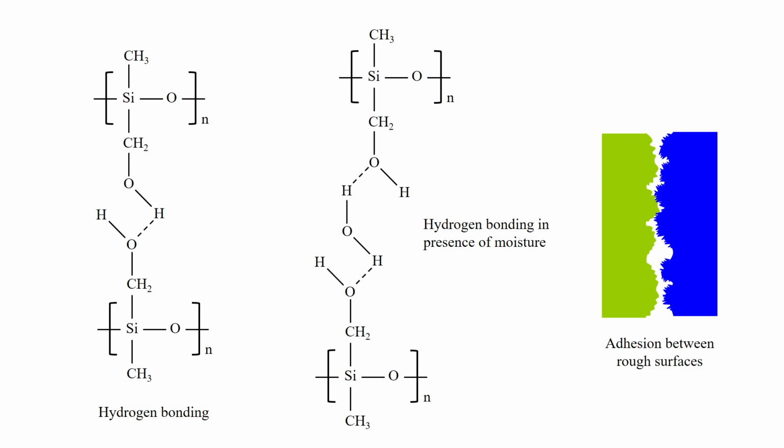Hydrogen bonding in presence of moisture can also happen, because H2O has got this OH and it can form bonds and like that, that can also lead to this kind of phenomena. The presence of moisture can play a role when you have this kind of rough surfaces, because water can actually go and form a meniscus, okay, between these asperities. So, the surface has got these asperities and there is a large curvature there. So, the moisture can go and condense over here, okay, by Kelvin effect. So, quite many complicated situations may arise, okay, which deserve attention.